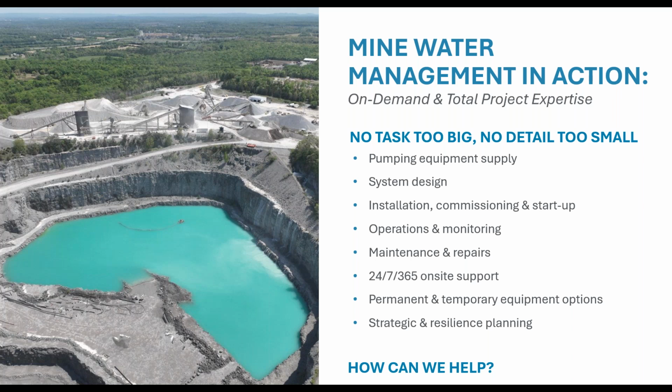The removal of those animals and additional silt from the sump after the rain event would be handled externally, but we could certainly assist in that. But I would say if that is a concern, then the addition of some fish screens would be a quick way to protect the pumping equipment from the animals, or rather protect the animals from the pumping equipment.